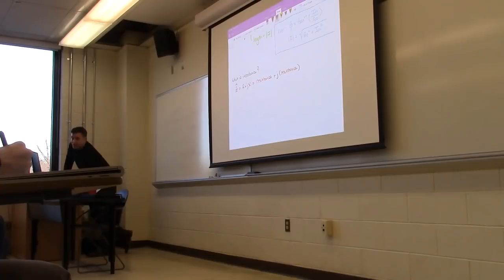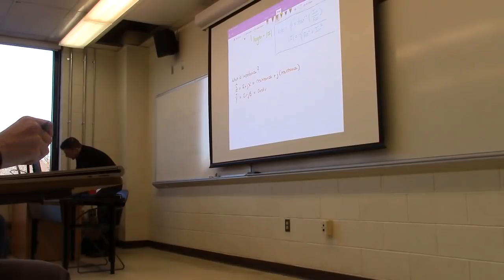You may do that sometimes for calculations. There's no inherent names for, at least not that I know of, those two components. Okay, then we have Y, which is our admittance. That's equal to G plus JB. And so that's going to be conductance plus J times susceptance.